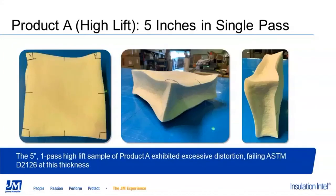Now that we've seen how Corbond III performs, what can a high-lift product look like after hot and humid aging? The answer is not so great. The sample was sprayed according to the manufacturer's instructions, including spray parameters and pass thickness. Still, it resulted in significant distortion and had a volume change of over 30%, failing the acceptance criteria.